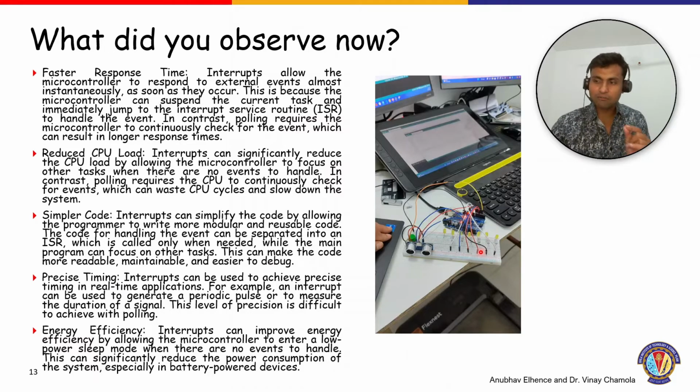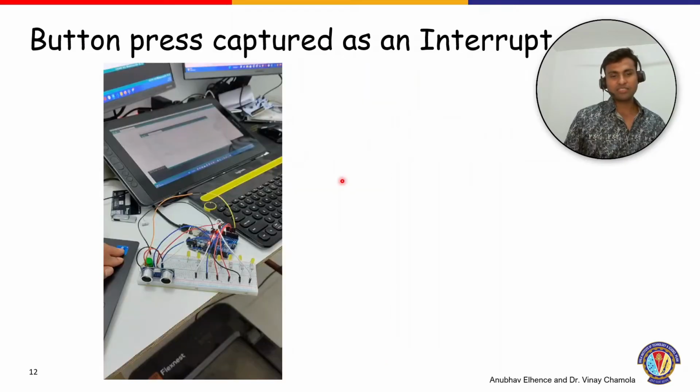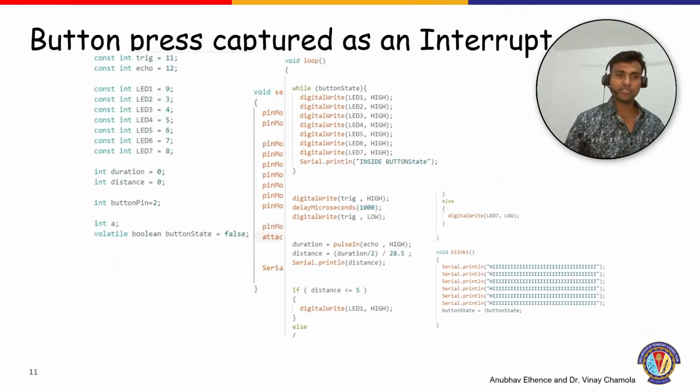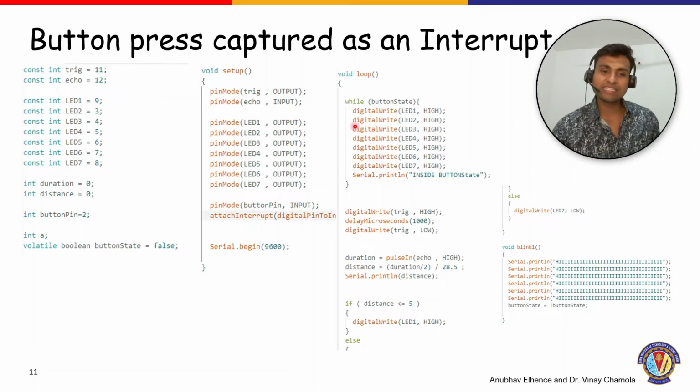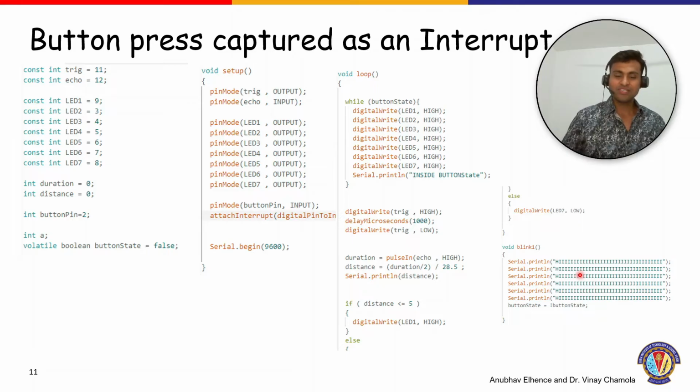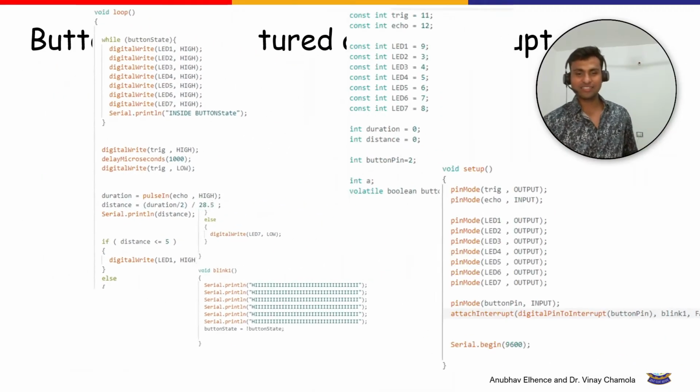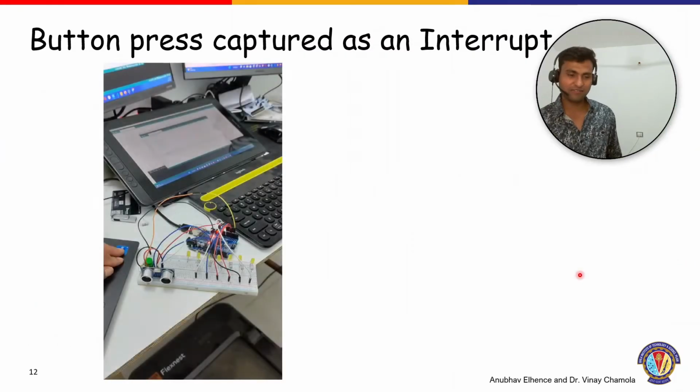So one button miss, you might have observed in the video, and there is a perfect reasoning to that. But the interrupt in general has not failed. Every time I press the button, the interrupt was raised, and I could see it in the serial monitor. And let me just tell you very quickly, since I have already raised that point: what if I'm already inside this while loop when the interrupt is raised? So think about that. I've not modeled it perfectly, so that is why you might have seen some glitches in the video.